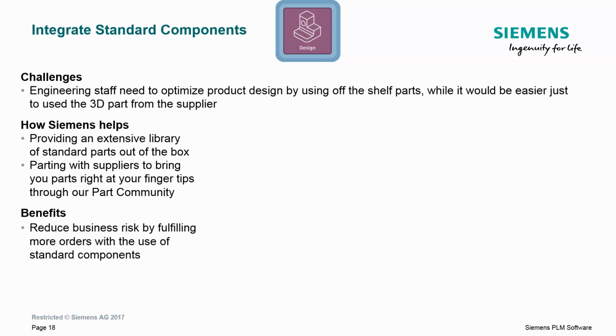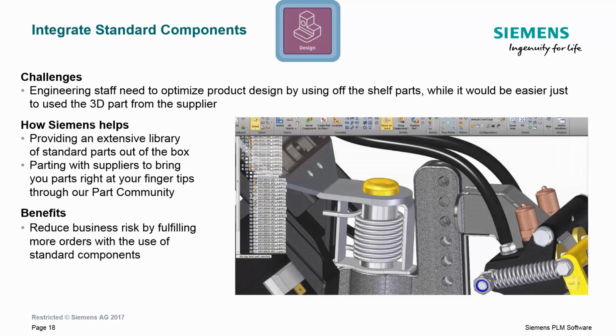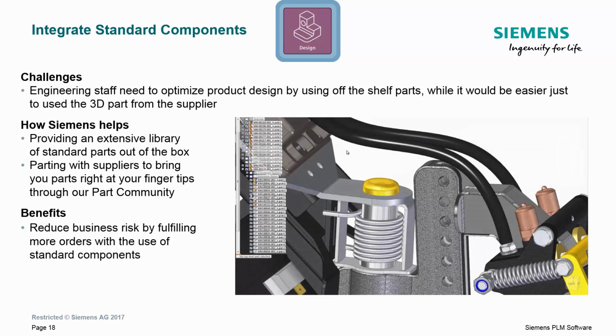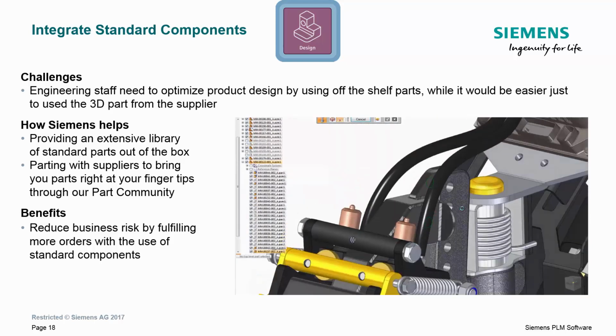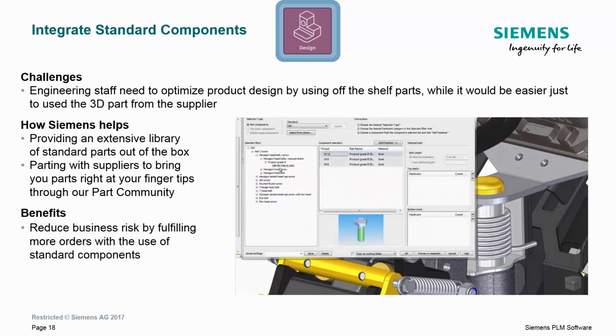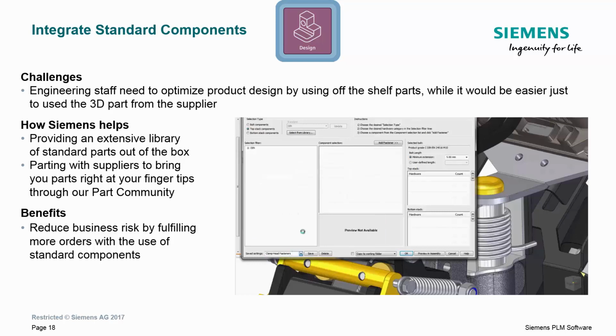As is true with most assembly designs, there need to be fasteners to bolt, screw, or pin components together. Solid Edge provides an extensive library of fastener components based on any common standard and automates their creation and placement. This automation saves designers lots of time and headache, not having to model and place the fastener stacks individually. These stacks of bolts, washers, and nuts are automatically determined based on a selection of entrance and exit holes in an assembly.